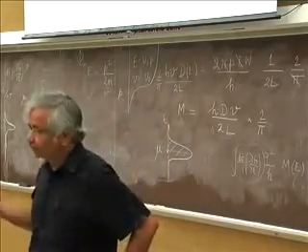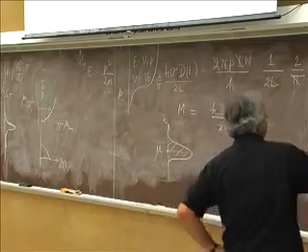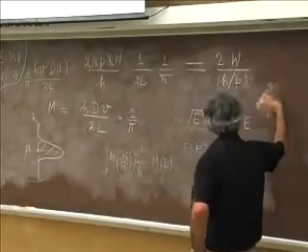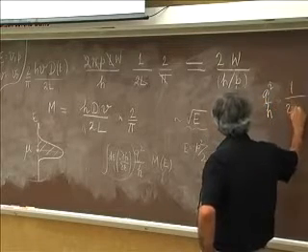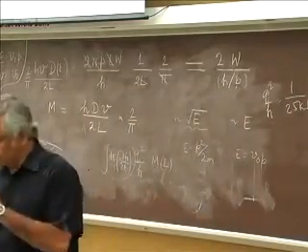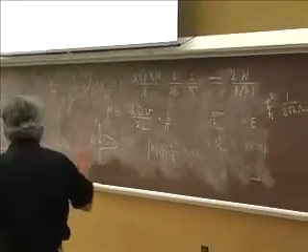So when you look at the ballistic conductance, for example, what is the quantum of conductance? It's q squared over h. Or if you invert it, h over q squared, that's like 25 kilo ohms. Now, if you actually measured the conductance of a small piece in gallium arsenide, what you get is not 25 kilo ohms.